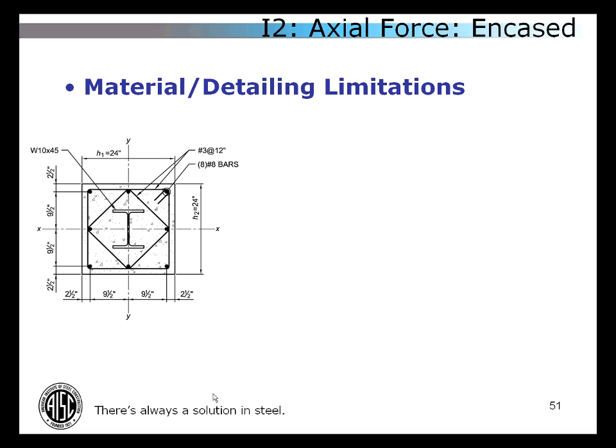Sure. What I was talking about here is instead of placing the longitudinal rebar along the XX and YY axis like you see here, just take those bars and push them out to the corners of the concrete so that all your longitudinal reinforcement is placed within the corners. You can achieve that by either using 4 bars that are large enough to handle the load that you're applying to them, and if that won't do, you could use bundles of 2 to 3 bars that are in the corners.